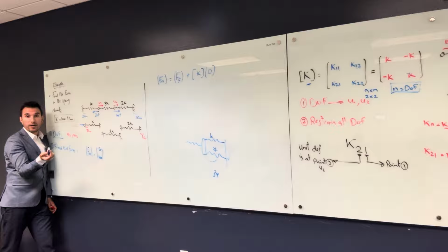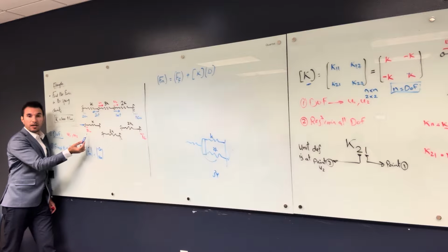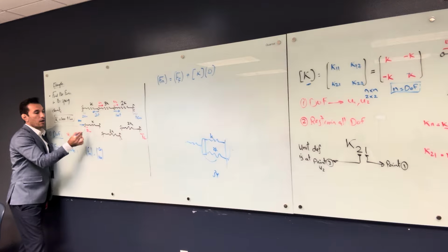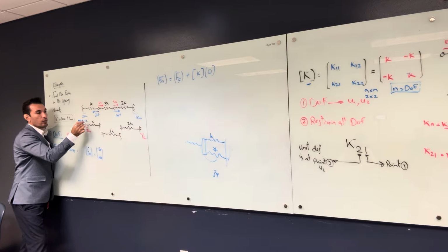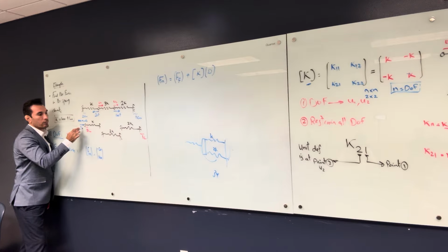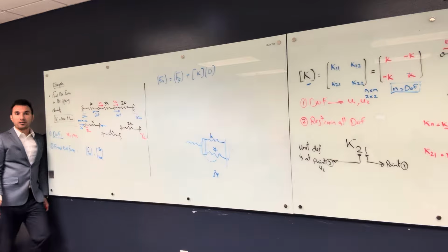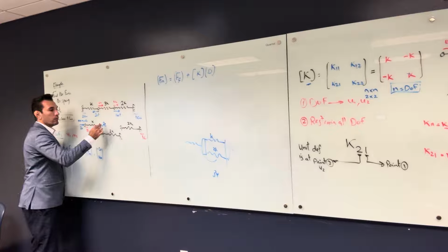K multiplied by delta, right? So the force is K multiplied by the 2 centimeters. K delta is going to be 1,000 multiplied by 0.02. So it's going to give you 20. But definitely this is going to trigger a reaction on the other side, equal to another 20.